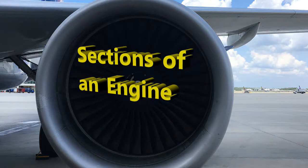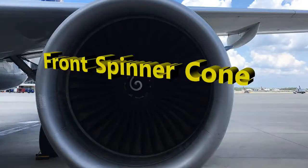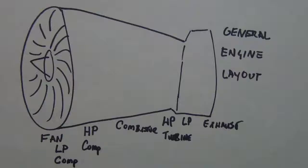In the front part of the engine, you have the fan cowl, the air inlet part, which has a spinner cone, which is the front spinner cone. You also have a rear spinner cone that's attached to that. That's part of that front part, that fan and booster section. The booster part involves the low pressure compressor. That's what the boost is. After that first stage, this is about the power of air and being able to produce thrust using the engine, obviously.